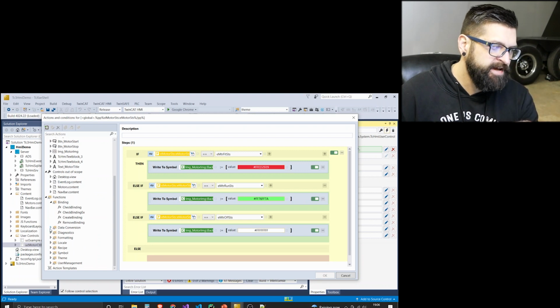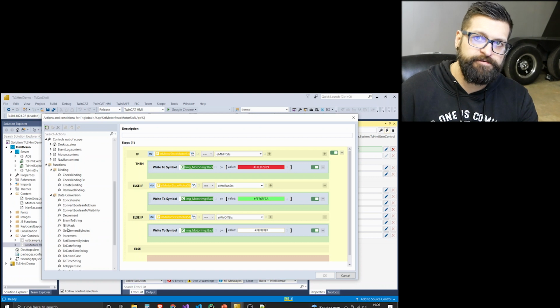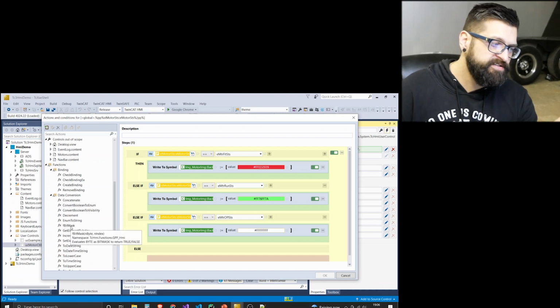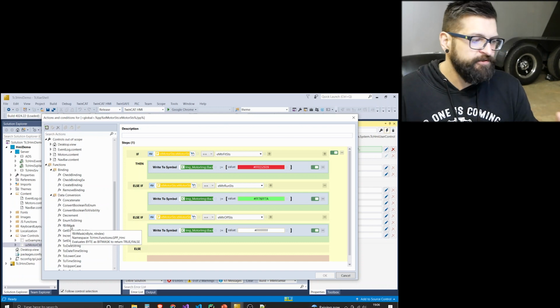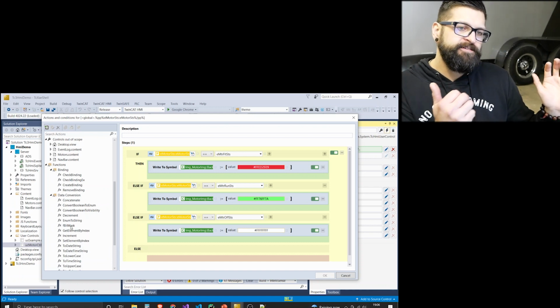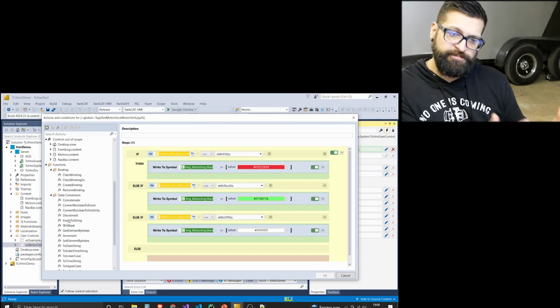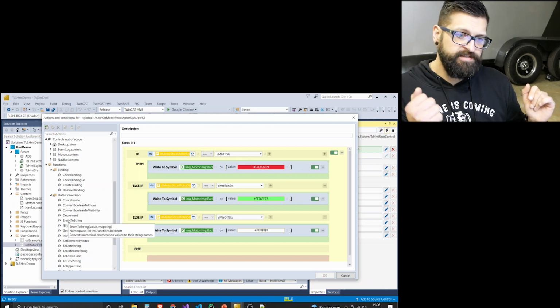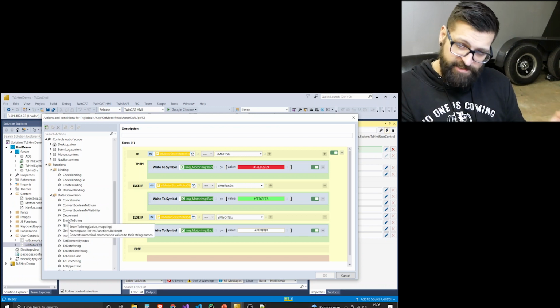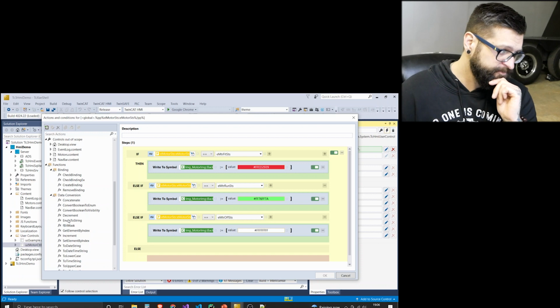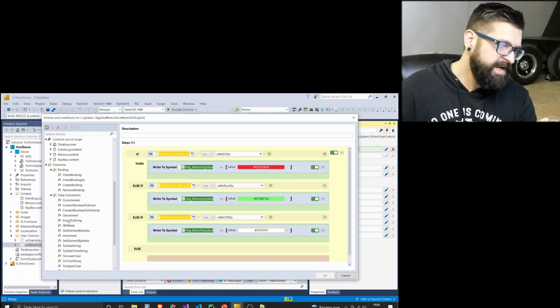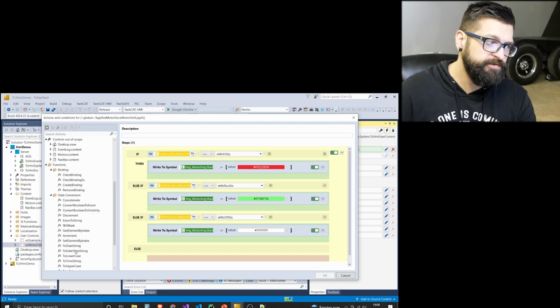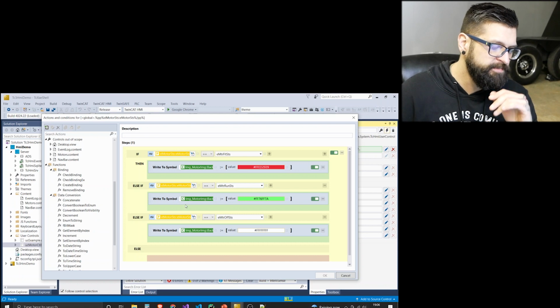So fBitmask is a custom function that I created. It's a JavaScript function that works inside the TcHmi framework. And it doesn't matter what the scope of that function does, but just know that if you have some function that you want to use repeatedly to change the properties of an HMI control, you can write custom functions and use them here. And then you would just drag and drop them over into this work pane in the middle.